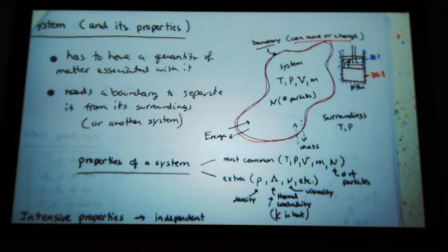But in this case, I can draw the boundary like that, but it really didn't change. I could break the volume within that boundary into two parts, one of the cylinder and one of the gas. And then you would see after inspection by breaking it into two parts that the volume of the cylinder part didn't do anything. So it really was just boundary work associated with the gas, while the piston did move. Now if I have thermal expansion, that comes into play, that's a whole other issue. So there's a lot of systems where you can have changing boundary conditions not associated with what we really want, but some component of it. And then you need to take that into consideration when you look at efficiencies.